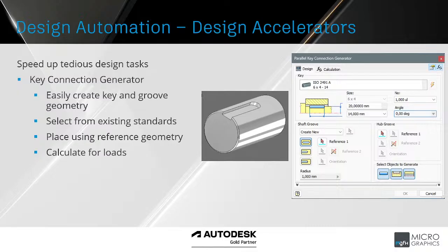Second one is, as I mentioned, the key connection generator. In this case, we're looking at speeding up that tedious design task of having to model in the keyway and then also modeling the key and placing and constraining the key. In the case of the key generator, it allows you to easily create key and groove geometry.